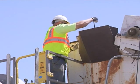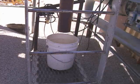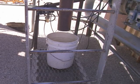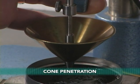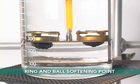Sampling during production and construction is relatively easy and inexpensive. It is rarely necessary to test every sample obtained. Use standard practices for material testing as per conventional HMA. Additional rubber asphalt tests include cone penetration, resilience, and ring and ball softening point.